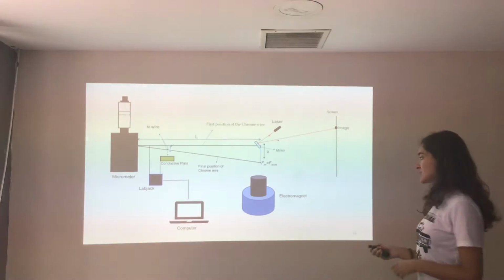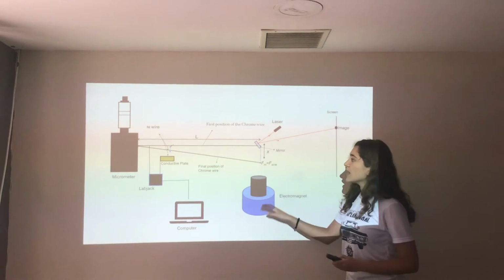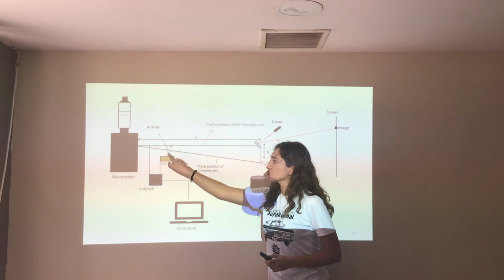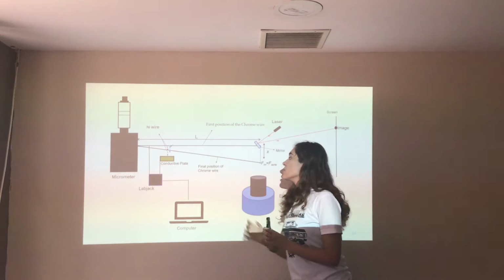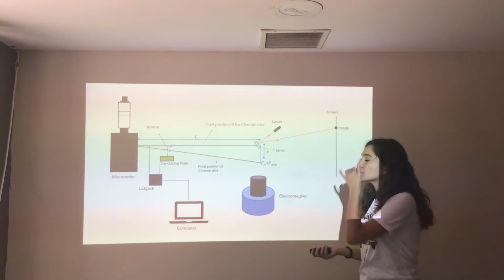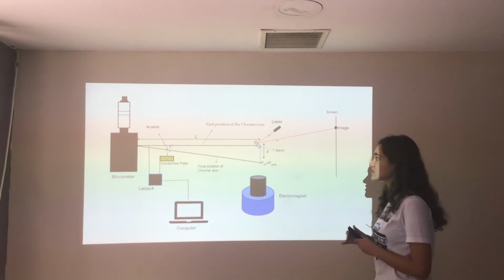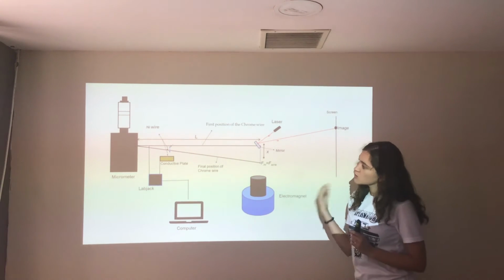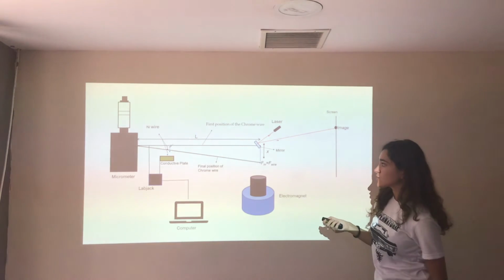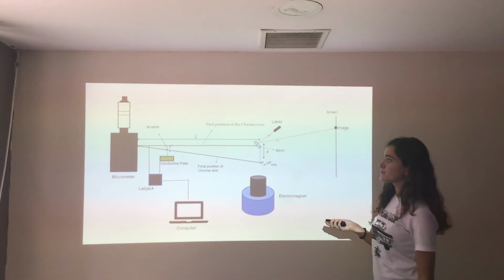In my main system, there is an electromagnet under the chrome wire. And there is a nickel wire fixed on the chrome wire, and it is perpendicular to the conductive plate. And you can see my circuit in this part. When the electromagnet affects the chrome wire, the chrome wire is pulled down. So the nickel wire is pulled down too. And it creates a nanocontact between the nickel wire and the conductive plate in this region.